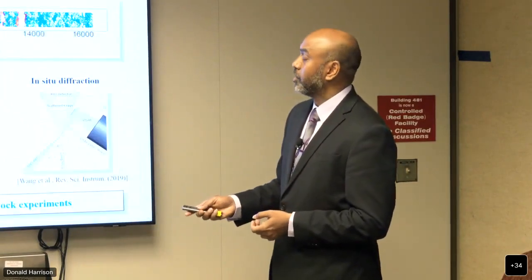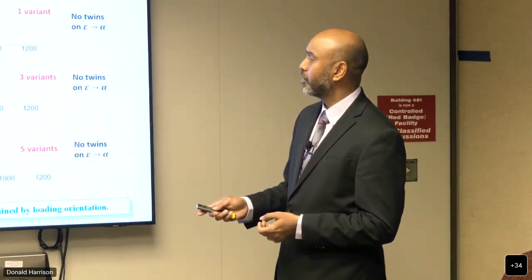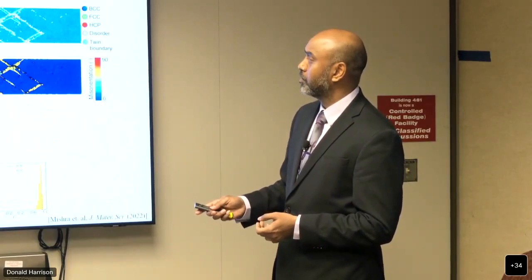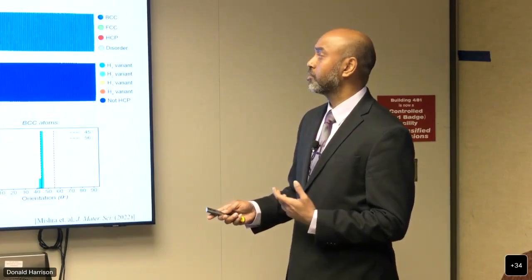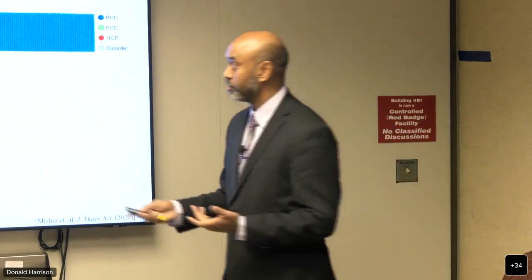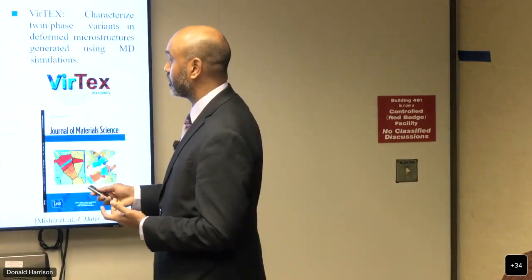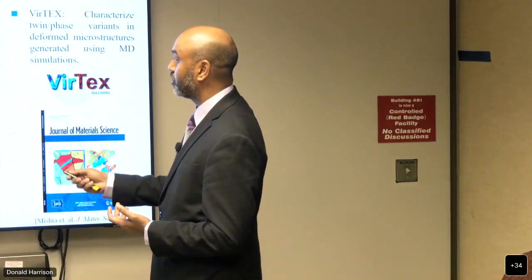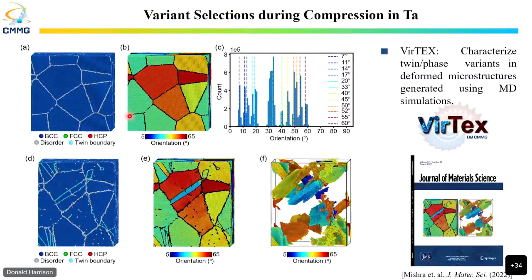And can you control that by adjusting the shock? I have a nanocrystalline one here. So our nanocrystalline systems in MD, or the polycrystalline systems in this, these are all based on random orientations. So we build the structures using Voronoi tessellations, where we specify grain size and we specify a random orientation. But if you want texture, we have done texture where we say you want a certain texture orientation in the system, and we can build those things.